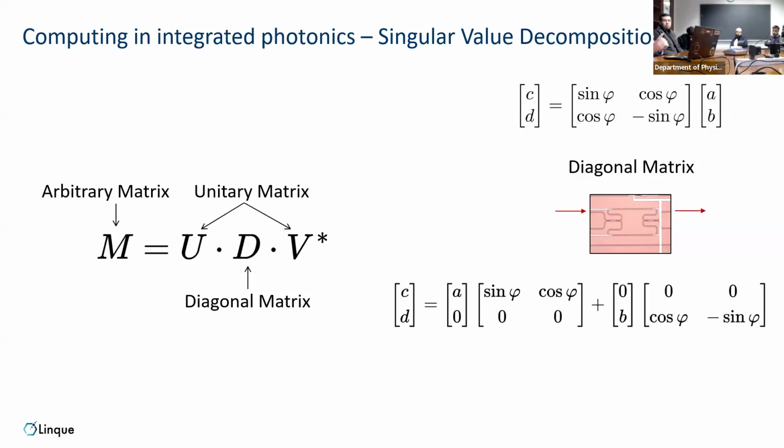The higher the precision, the better the digital one gets in comparison, especially for efficiency and power consumption. Because the higher precision you need on an analog system, the higher your signal strength needs to be with regard to the noise, because you have to resolve all these different steps. So the analog system is best when you have low precision. And that's why we never tried to go beyond 8-bit. But this we achieve.